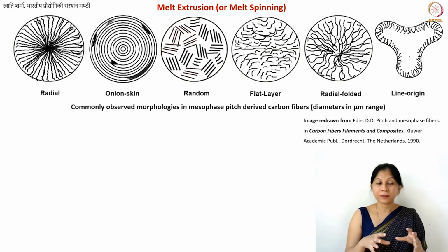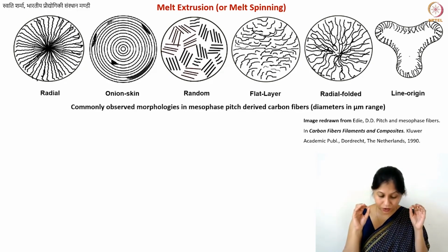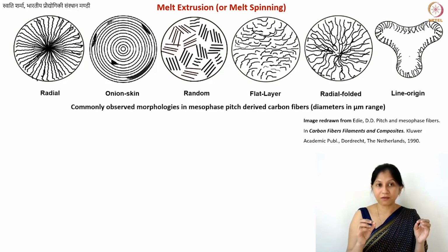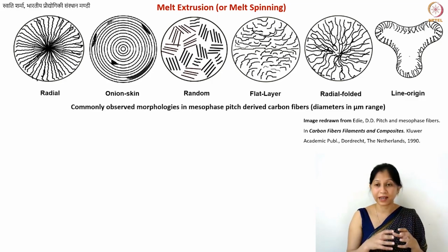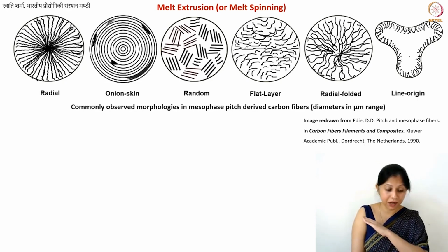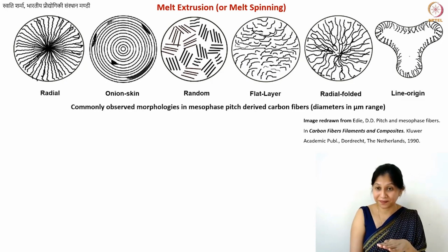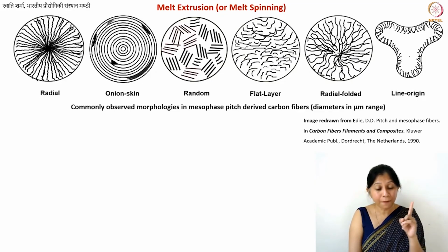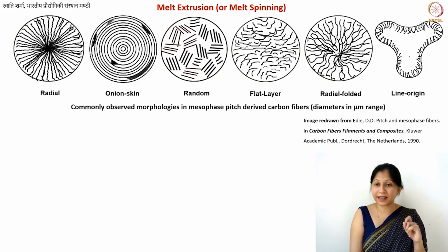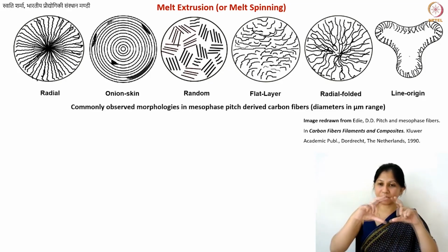So in the case of carbon fibers, when we talk about graphite fibers, even when we use the term graphite, we may not have the perfect ABABA organization. Here we call a fiber graphite when it has just a very high graphitic content. Even so, you have the large La value, large crystallite size. The Lc value is a little bit tricky in the case of fibers because you do not have these perfect crystallites.